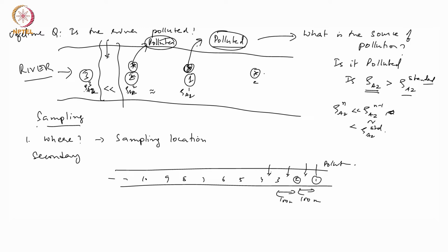So what she is saying is, instead of sampling randomly at 100 meter distances, you go and look at what is there on the shore, on both sides, what could be possible sources of contamination. Is there anything physically that can contaminate? We call these point sources. Point source is used in air pollution predominantly, but we use it here for water pollution too, which means that there is a fixed source here.